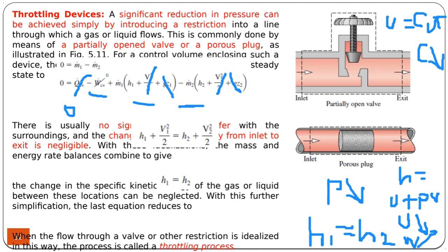So if the temperature becomes much smaller, it means that the refrigeration or the cooling has already started, and it continues in the part of the system, the refrigerating system, called evaporator. But it initiates the cooling by expanding the liquid into low pressure, where it expands and actually it starts to evaporate. And during the evaporation, it absorbs heat from the surrounding, meaning that it starts cooling the surrounding.